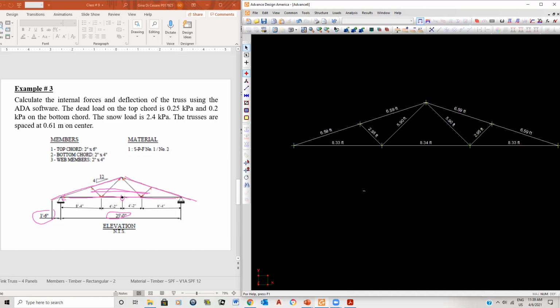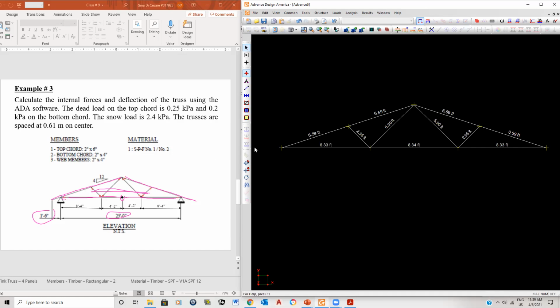Then, if I want to create, for example, this overhang here, all I've got to do is add a node there, and I just need to know the coordinates of those nodes. Here it's minus 1.5 feet, and it drops down by 6 in 12. So this drops down by 0.5 feet there, and if I know the coordinates here, I can create those two nodes.